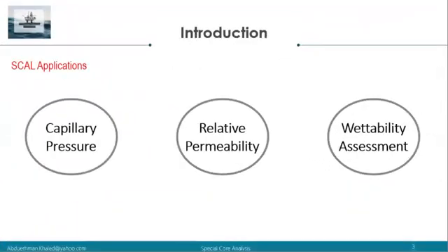So let's start. Special core analysis is the essence of the evaluation and management of hydrocarbon reservoirs. And high quality and reliable data will allow us to maximize the performance of the reservoir, by understanding different aspects. For example, here we have the capillary pressure, where we can build the saturation height models for the hydrocarbon in place determinations, and also find out the best correlation for the pore throat size distribution.